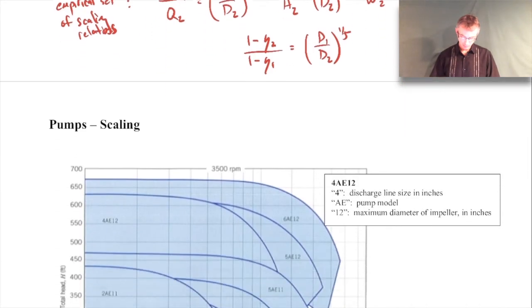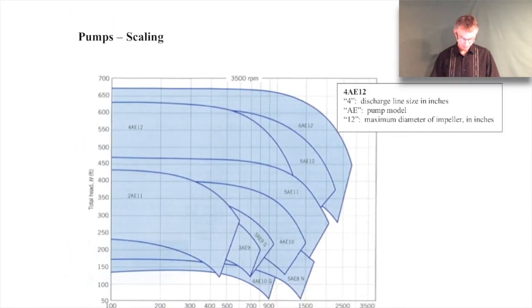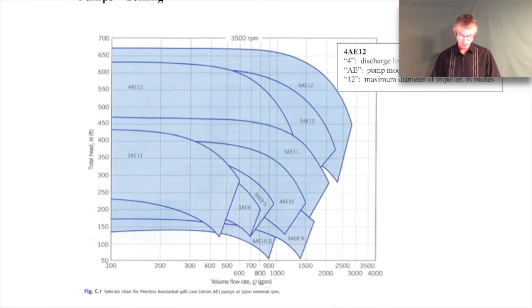All right. I have one more thing I wanted to talk about. And this is just a plot showing you what kind of pump model number would be most effective for your particular application. So, many companies make more than one type of pump. They make a whole bunch of different models of pumps for different applications. And it's helpful to be able to figure out which model numbers are most appropriate for your given application. It'd be nice to be able to narrow it down. Now, the first thing you could do is to look at the specific speed.